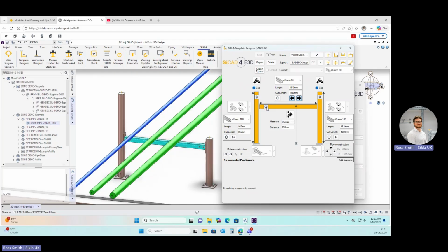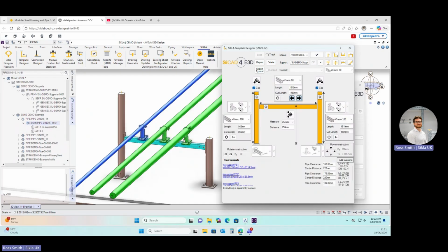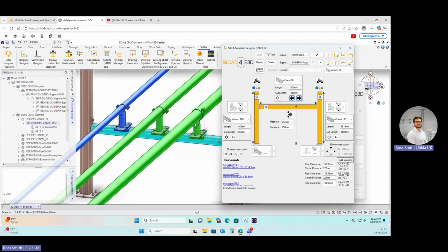I will, this button here, the magnifying glass, I'm going to right click on here and say, okay, within the vicinity of my pipe support, or this crossbar specifically, because I've clicked on the magnifying glass on the crossbar, please add guided pipe shoes. Okay. You can see that instantaneously, regardless of the size of the pipe, an attachment has been added. And they've all got guides on.